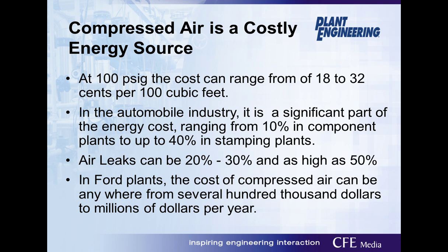But the whole thing is you have to take the total cost into account, because there's also ancillary equipment that goes along with the compressed air system. So this cost isn't just about what the air compressor uses. Remember, you have dryers, you have aftercoolers, you may have intercooler cooling. So it really depends on what it is and how much it works.